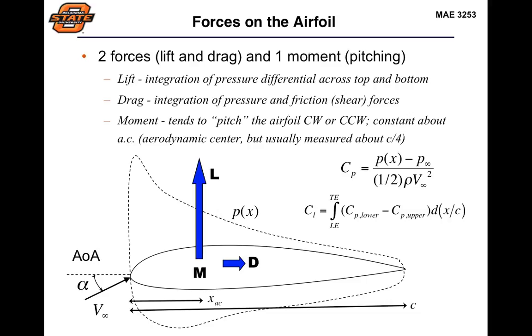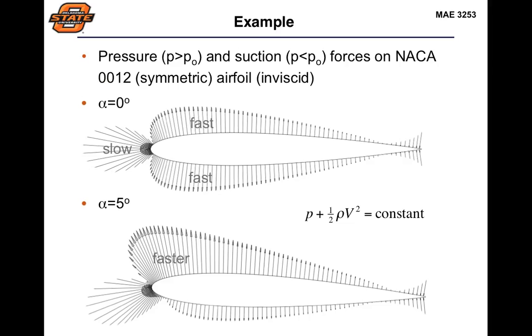Now, when we're calculating the inviscid value of our airfoil parameters, we'll get a lift coefficient which is based upon this pressure field, and we can also get a pressure drag coefficient. It's very important to note that even though that lift coefficient will typically be pretty close to what the viscous lift coefficient is going to be, that drag coefficient will not, because it's really our viscous forces that are going to be dominating the value of our drag in most scenarios.